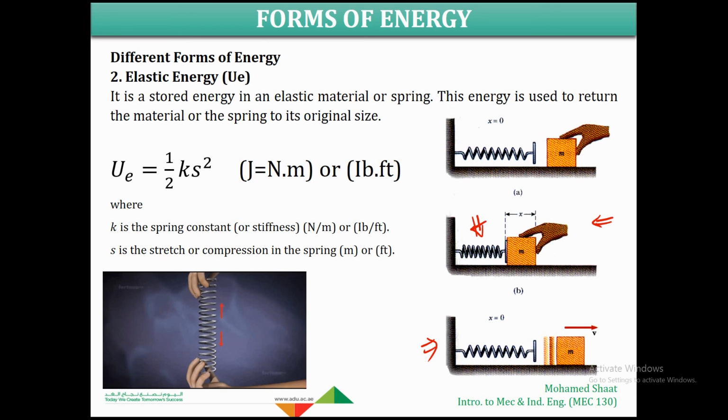This energy is known as elastic energy. So that's why we are giving the name elastic, because it works on the same concept as the elasticity, compared to the plasticity, when we were discussing the stress strain curve or the tensile test of the material. We said that within the elastic region, the material can restore back its original dimensions, and this requires energy.